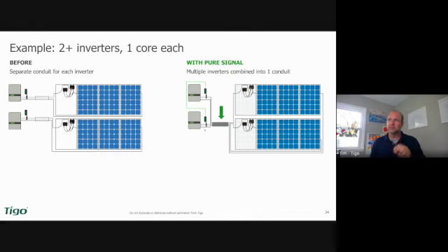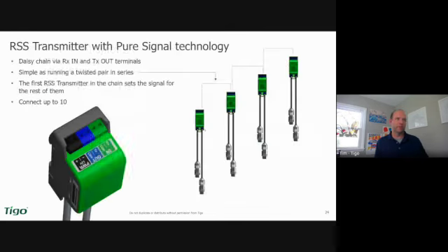But just take a mental note here. If you have a customer asking for the rapid shutdown devices only, flag that in your mind, because we want to make sure that the systems are designed and installed properly. We'll talk about it in a bit, Green Glove and Tigo Academy, and we have a ton of information at their fingertips there to support them. But with that one, we want to make sure that they don't unintentionally cause a situation where they could have crosstalk.